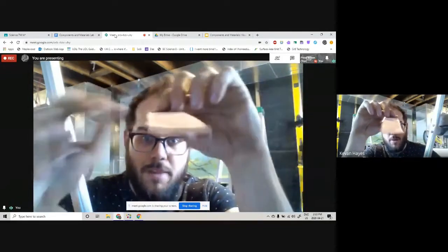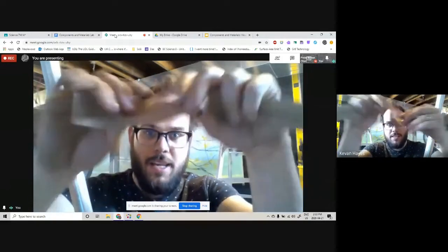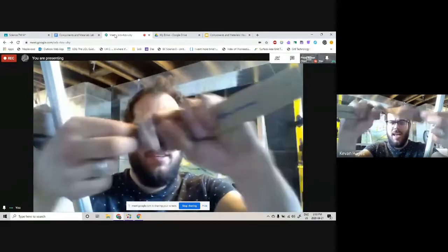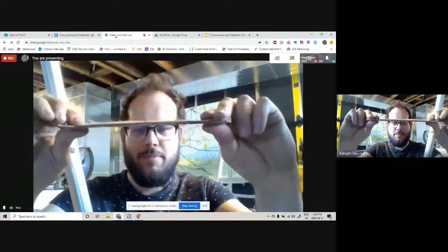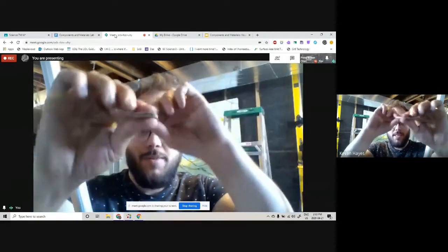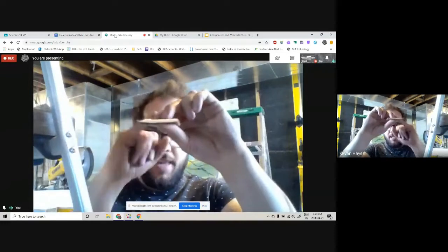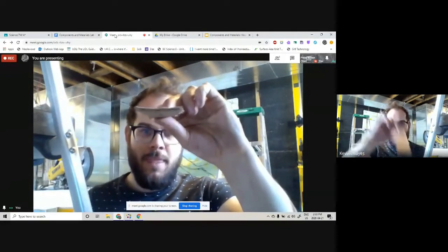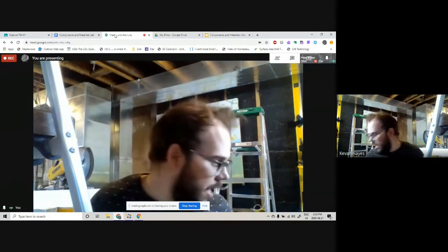Now, if I just take one layer of that paper off, like here's just a top layer of a piece of cardboard, this has no structural strength at all. Whereas 3 pieces of that paper put together form something that's pretty strong for how light it is. And the reason is all about that layer of corrugation in between. So corrugation kind of works the same way that a beam works, right?